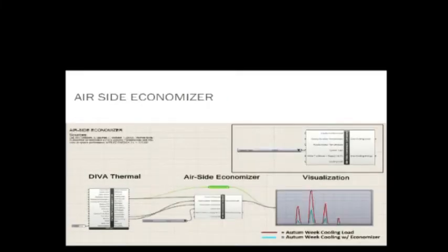So then we looked at also the economizer. I believe the thermal component doesn't have economizer capability, but in some of the cold regions, it's quite used. It's very standard. So basically what we do is we are looking at the outside air temperature and the high dry bulb limit for which, above which there will be cooling load, below which there will be heating load.